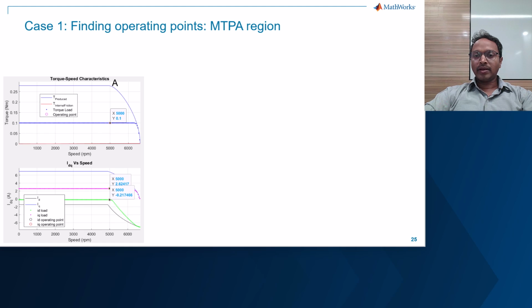The dotted thick blue line represents the speed torque characteristic of the motor when the motor is operated at a reduced current limit to reach the demanded torque. This curve is plotted to see what the operating currents are for the motor under the speed torque operating conditions. The bottom left figure shows the currents ID and IQ drawn with respect to the speed corresponding to the speed torque envelope points. The thin solid line represents ID when shown in black, IQ when shown in blue for the original current limit for the system. The thick dotted lines represent ID when shown in green, IQ when shown in magenta.